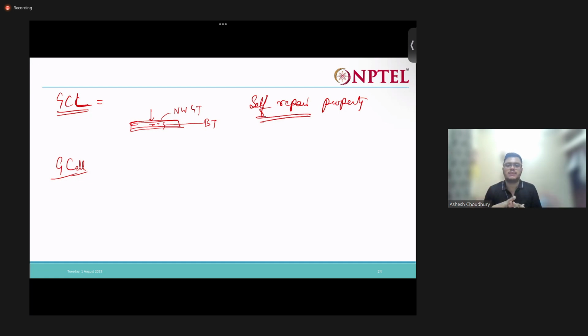Due to that, the soil actually gets strengthened, so it does not allow the soil to settle or anything, right? It strengthens the soil. So the main property of geocell is that it's a confinement product. It reinforces the soil with the help of confinement. Just in a simple way, if you want to understand this confinement property, say you have a soil specimen.